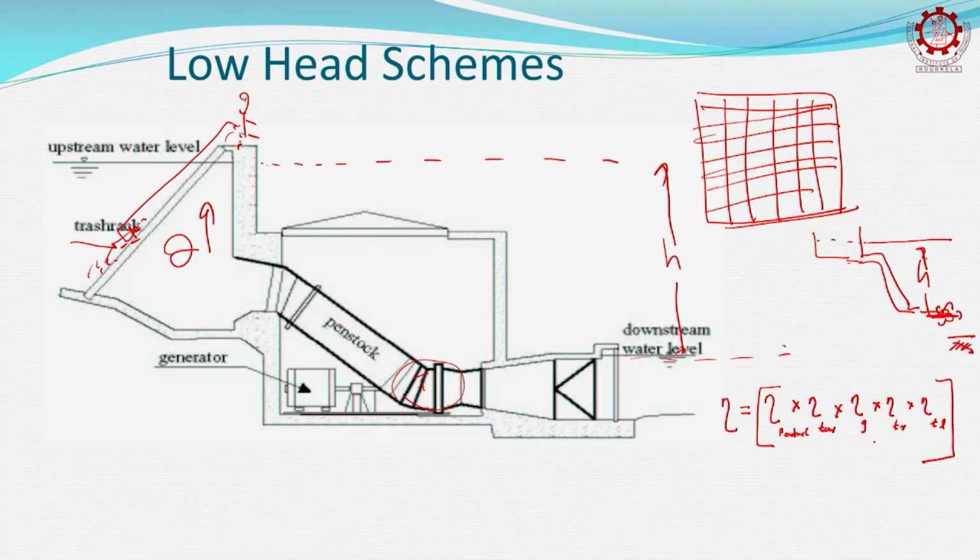Typically, if you look at efficiency, the penstock will be about 95%, that is 0.95. I will skip turbines. Generator will also be, as electrical engineers we all know, about 96% efficient, present day generators. Present day transformers are about 98% efficient typically, right. If you take the transmission line, again it may be 97%, maybe 3% loss for the transmission line alone, right. So why I skip turbines is, turbine is totally different.